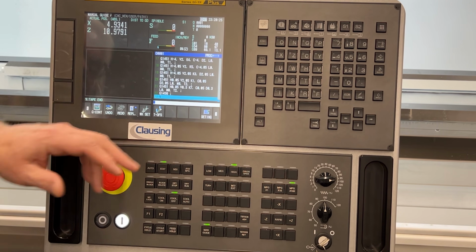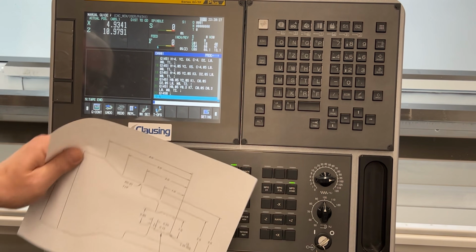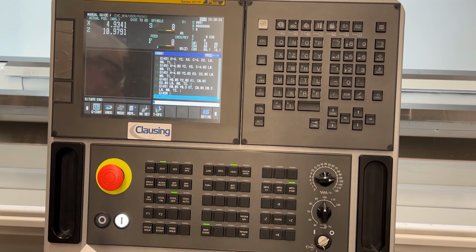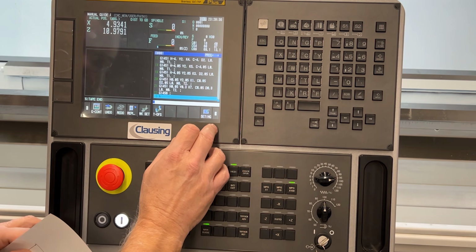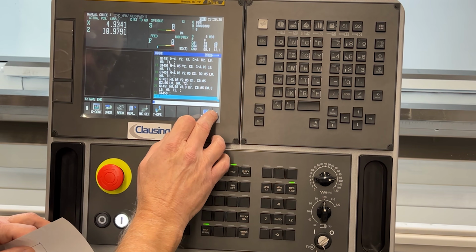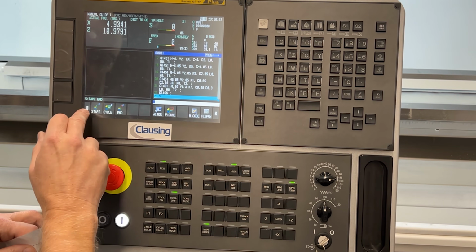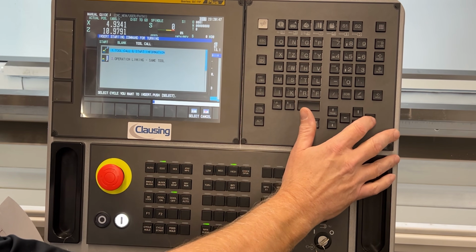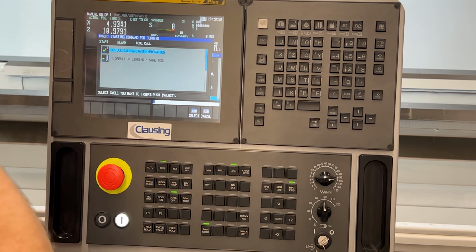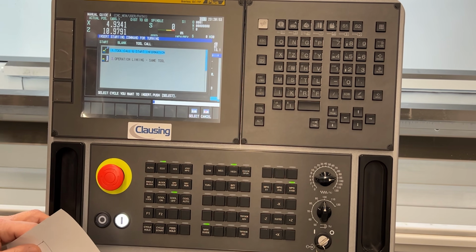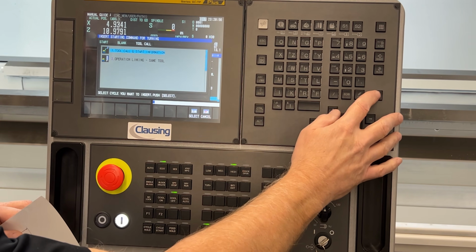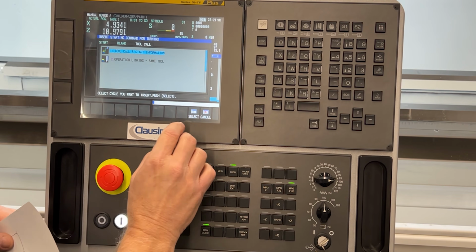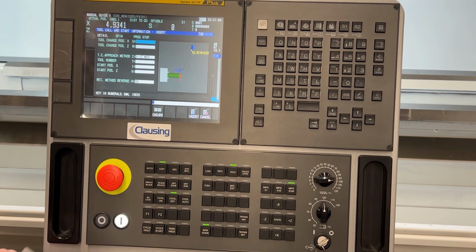Where we last left off, in this case it was line 23, what I'm going to do now is activate my tool so we can do the grooving cycle. I'm going to find my start menu and then go into the tool call. Again, this is developed by Colchester Harrison with Fanuc over in England, so this is just proprietary to this XS machine. I'm going to select the tool call there.